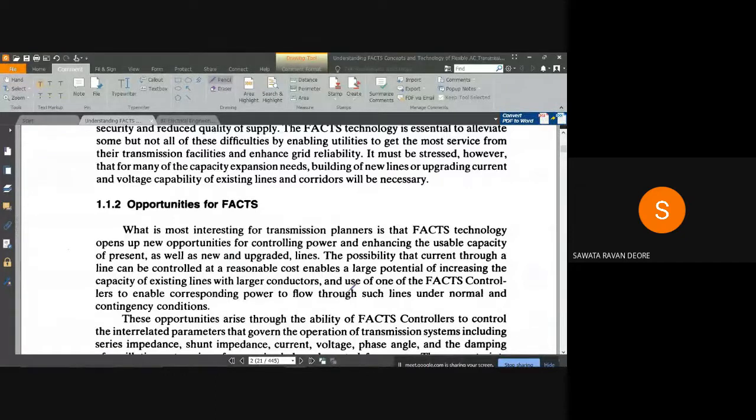According to the forecasted load, economical generation scheduling is done, meaning which generator will generate how much power and at what time. After that generation schedule, we do the load flow study to check, for that generation, how much power will flow through which line, whether any line is getting overloaded, and whether any bus voltage is going to cross the acceptable limits. So all things are first analytically verified, and once it is satisfied, then the system is actually operated with those considered power generations.